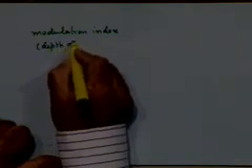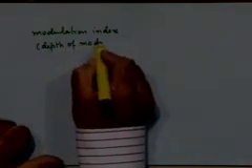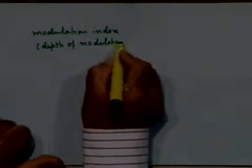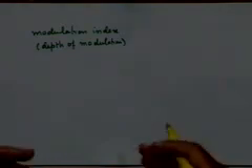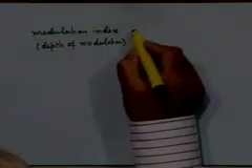So the alternative name is depth of modulation, which indicates this fact that the waveform either touches or does not touch. Basically, what is the relative variation of the envelope from maximum to minimum values, right? And that's precisely the way it is defined.